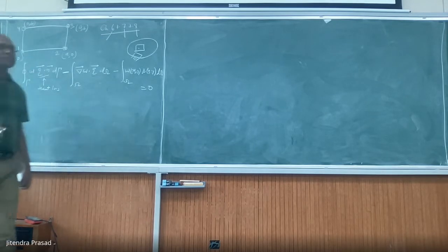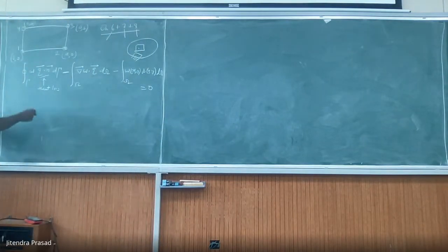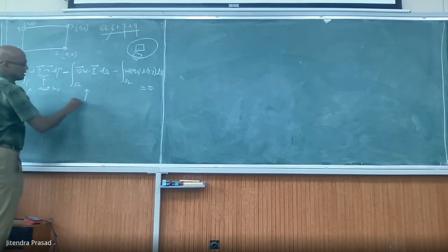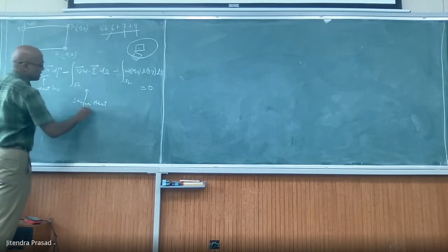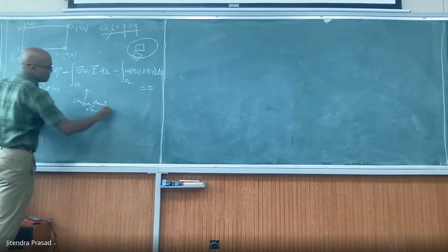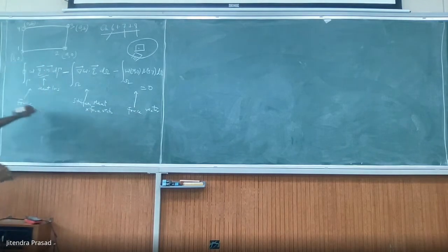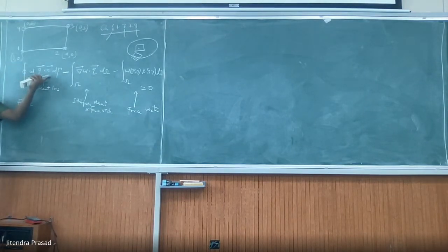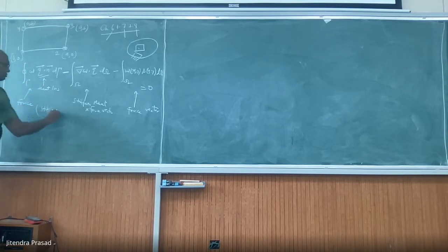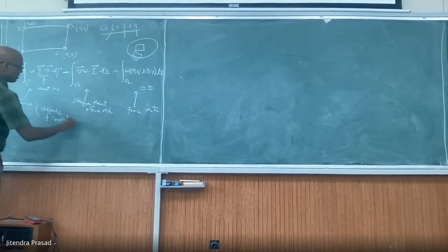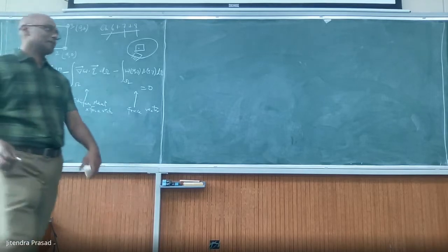Regardless of what kind of element you have, you will end up with this, which gives rise to a force. Basically, this one is a stiffness matrix, multiplied by the temperature vector in this case, and this gives you the force vector. Now, in this case also, as we have done earlier, there may be a convective heat transfer term. In that case, it may also contribute to the stiffness if there is heat convection. In general, we have seen that, right?